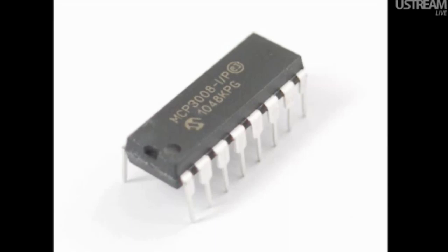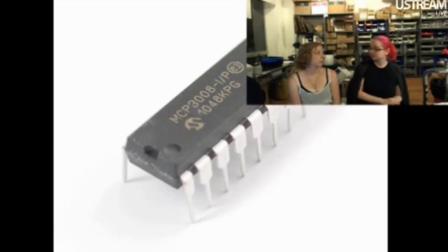So this is a really super easy way to wire it up. It uses 4 pins, and kabam, you have 8 analog inputs. And I wrote the Python code so that people can just copy and paste it in, and then you just read from the channel and it gives you 0 to 1023. So you can work with 10-bit, all kinds of sensors.